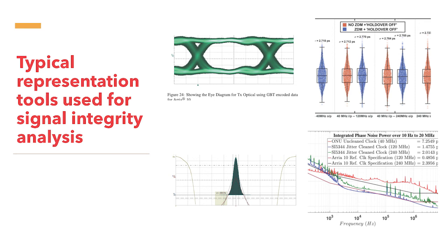The phase noise plot is used when you want to know, for a particular frequency, say for example 1 megahertz or 10 megahertz, what the phase noise is. And since these are all clock signals, all locked at a particular frequency, you are not that bothered about the jitter or noise present at other frequencies. So as I have already told you, the frequency of interest is 40 megahertz and multiples of 40 megahertz. Since I already know this from the experiment, I'm just giving you the figure for 40 megahertz.